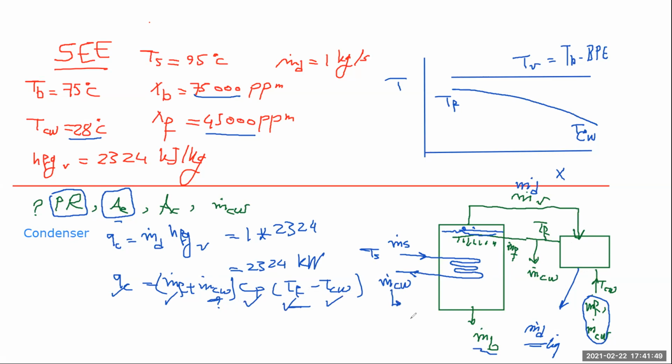This quantity will be calculated. It is 14.56 kilogram per second. Wow, this is a substantial amount. Remember, the m dot feed is only 2.5 kilogram per second, but you needed seawater of another almost 15 kilogram per second coming with it just to take care of energy rejection, to make sure that all the vapor which is coming is supposed to condense.